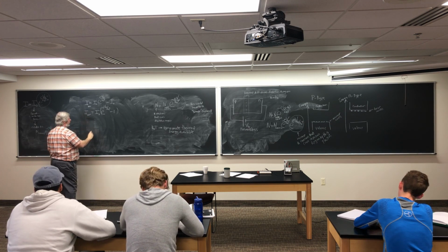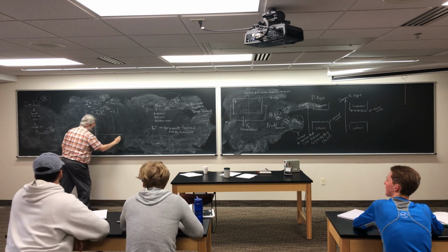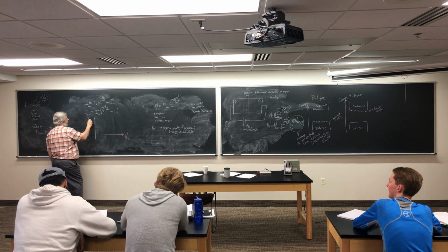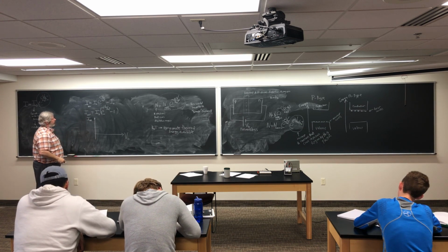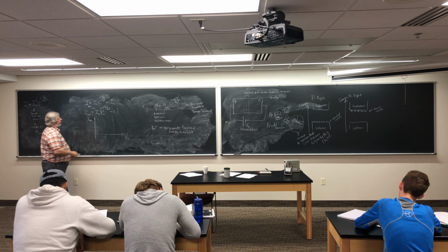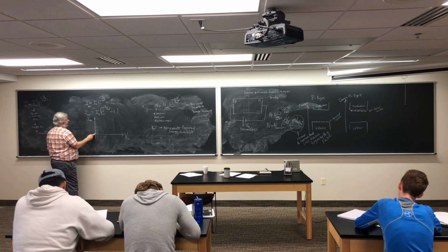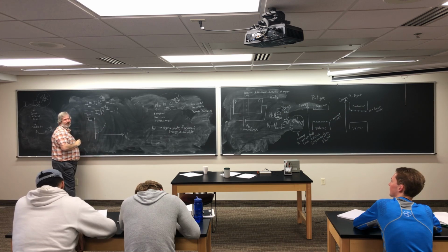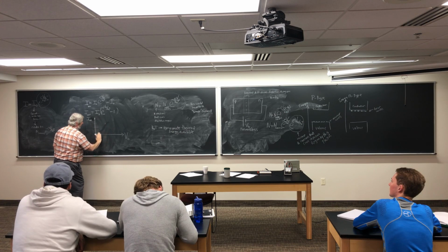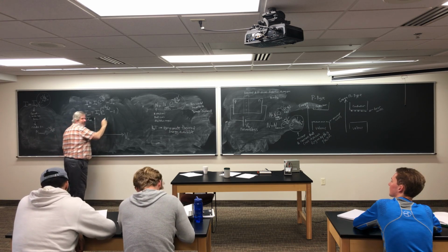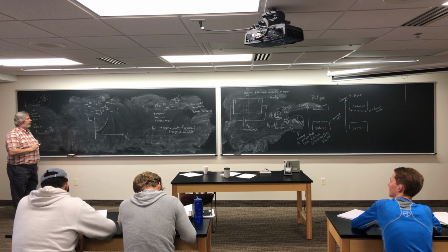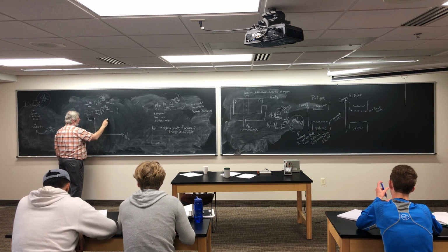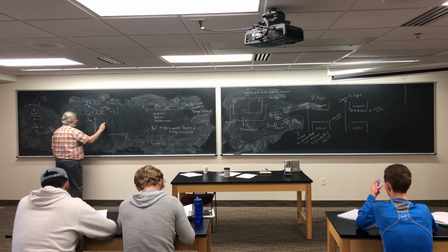Or any bias, actually. If you look at this, let's make this the bias voltage on this axis, and this axis is the net current you have. Really, this thing is going to look exponential as you increase the bias voltage, right? It might not start at 0 here, but it's going to go up exponentially. Actually, it's going to be really close to 0 because this is going to be small. So it's going to look something like this.